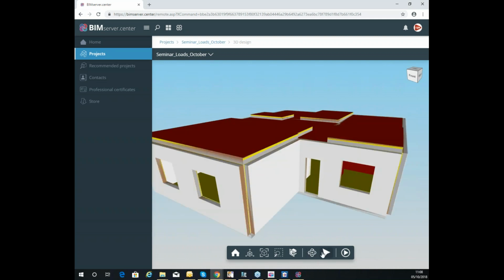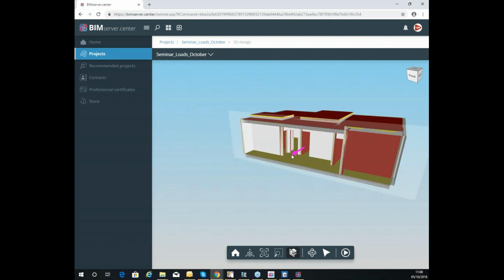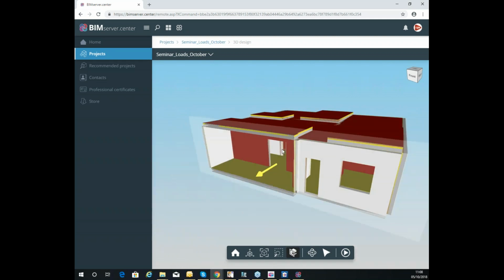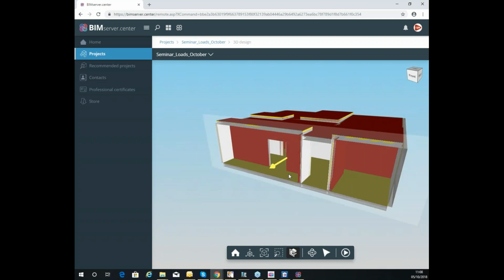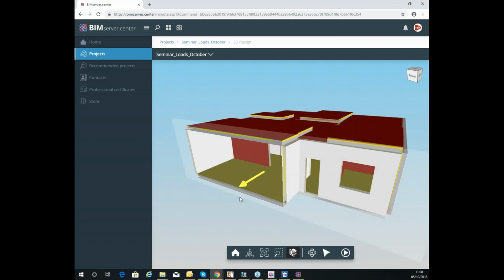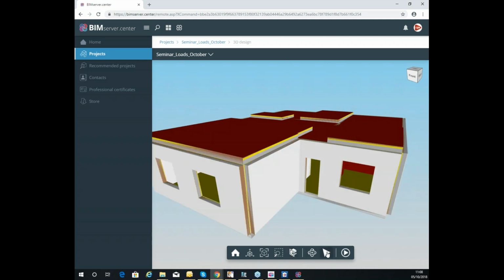And here there are some very interesting tools. You can see the inside of the different thermal models of the different stories of your building. And here also you can consult the different layers. For example, if I click here, I can see the roof with the thickness and the thermal resistance. For the wall, the same information. This is very interesting for the BIM managers, or for anyone, to verify that everything is done properly.